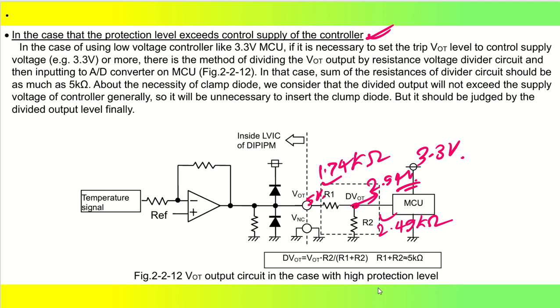Then if you want, you can send it to one RC filter, then send it to one buffer, and then send it to one ADC of the microcontroller. Or otherwise, for low cost applications or something like that, we can directly send it to my microcontroller.